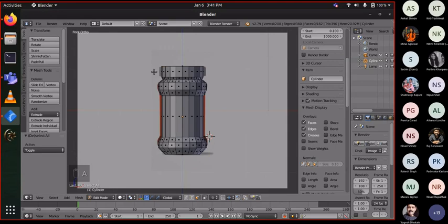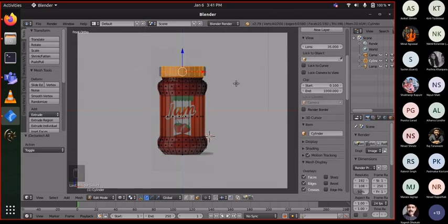And now we see the scaling is not as perfect as the cap. So what we can do here is switch back to the wireframe mode, and using the B key we can select the whole area, and scale and restrict that scaling with respect to the x-axis. So I think this should be perfect for the cap part.